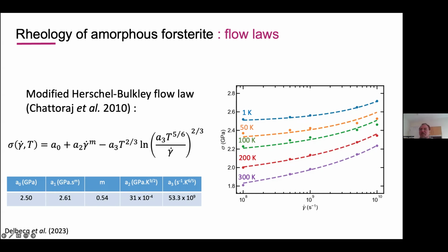Okay. And another question, this mechanism that you observe at the tip of the amorphous band, there is nucleation of dislocation, and then the band follows this dislocation path. This is similar to ductile fracture, but instead of dislocations, there are voids ahead of the crack tip, right?